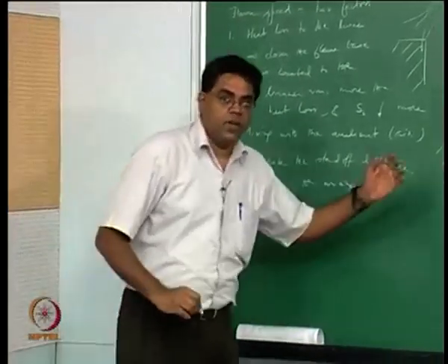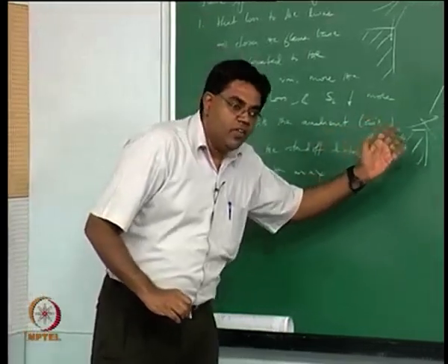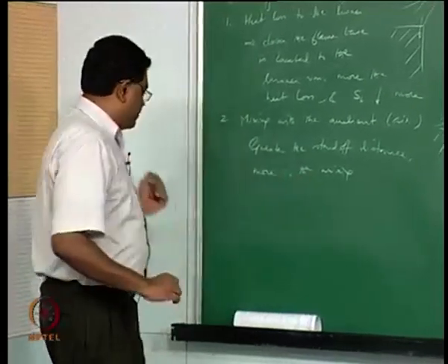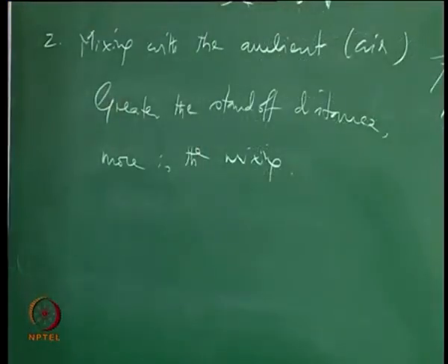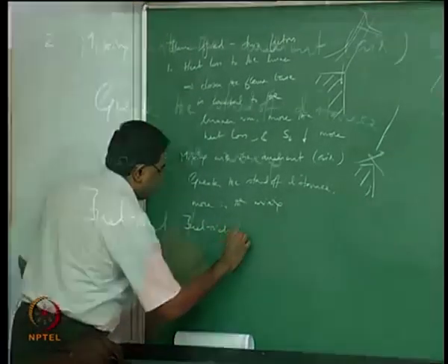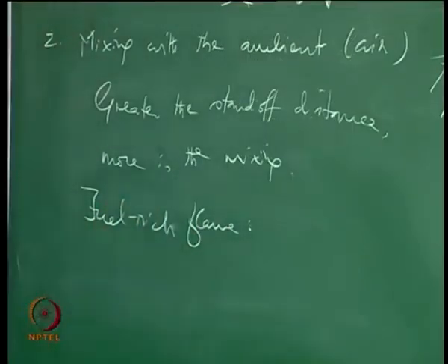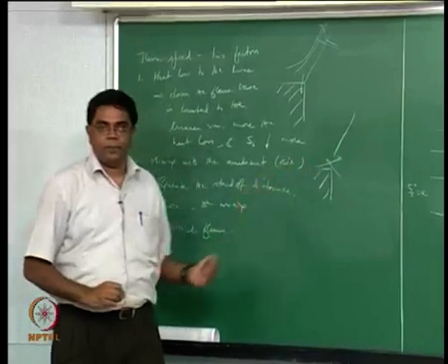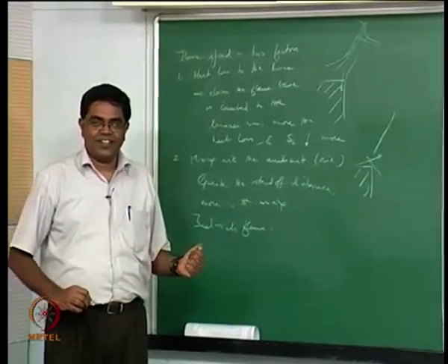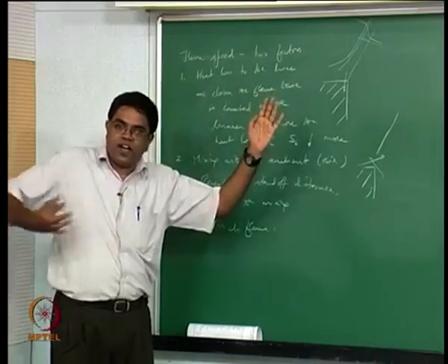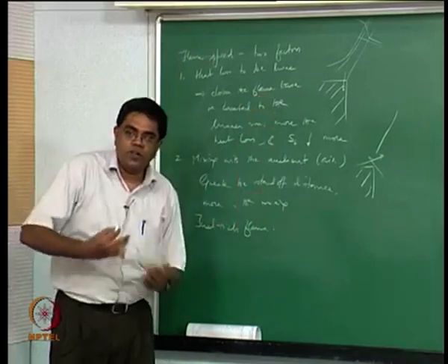And the question is, is that mixing going to be increasing the flame speed or decreasing the flame speed? That depends on whether the flame is going to be fuel rich or fuel lean. So, a fuel rich flame in an oxidizing ambience, what happens now? This region actually becomes closer to stoichiometric, because it is a fuel rich flame, and then you are now sending in more oxygen from the side, and therefore it becomes closer to stoichiometric.